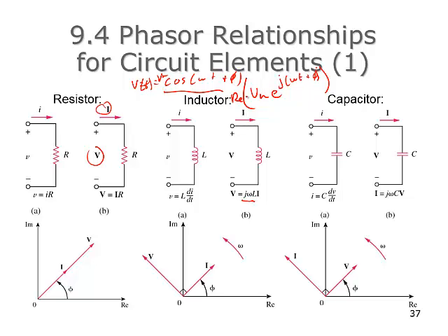Well, this is a complex number, and when we do the phasor transform, we normally throw out the time part because that doesn't really help us with the combination. We've got to combine these different signals at different phases. The omega t doesn't really play a role. But if you think about that omega t still being there, then the entire phase angle, if you call that theta, is omega t plus phi. Theta is growing linearly with time, and if you keep looking at it in future times, the phase of this thing starts rotating, right?